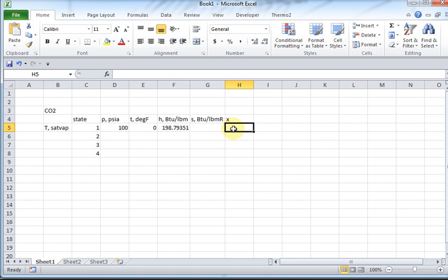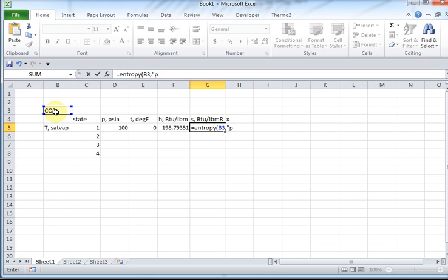But what we'll do is get the entropy. So I come out slightly superheated. That's probably what I'm doing. The entropy for CO2 as a function of pressure and temperature, English units. There's my pressure value. There's my temperature value. And good, that works. So forget about X. Well, I'll come back to X later for state 3. So now we're going to push it out. What comes down? S comes down. Whoops.